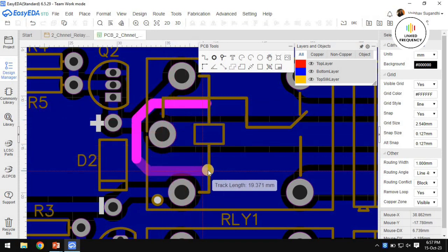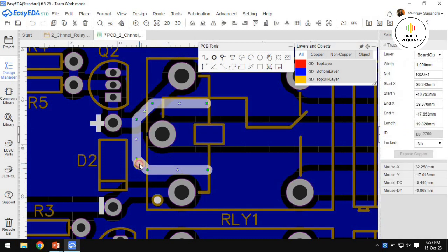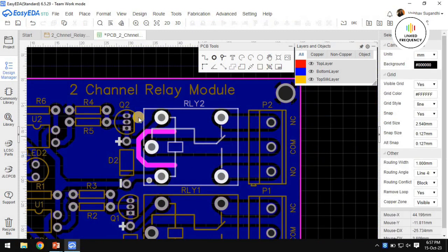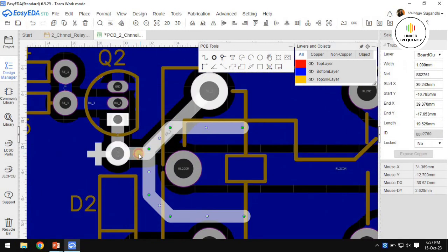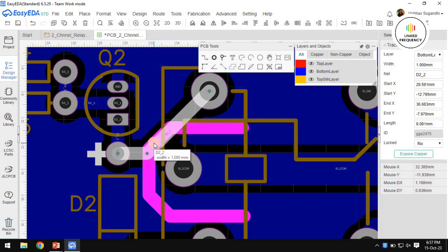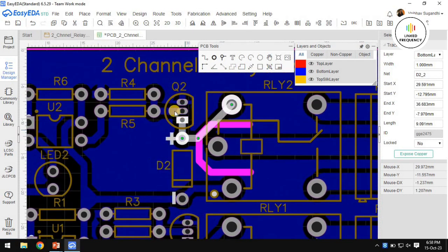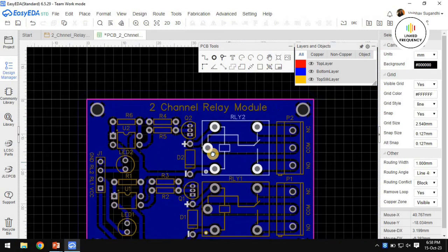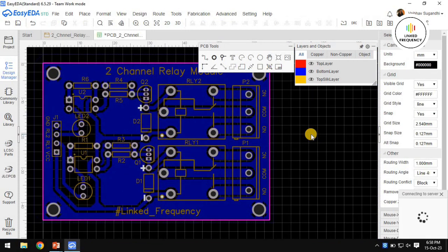Which you might have seen in real-time PCBs, right? These slits will isolate the entire DC circuit from the AC signal that we are switching by using a relay module, which I have not done here because of the track beneath that. To avoid that complication, we need to bring this transistor here, adjust the diode a little bit, and then add a creepage clearance. The concept of creepage clearance is essential and very important when you are dealing with high voltage signal switching with respect to digital circuitry.